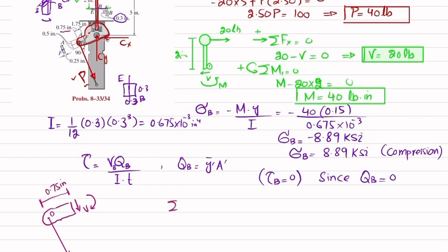So we will find the vertical force, sum of all forces along this direction, which is, this is your Y dash, this is your X dash. So sum of forces along Y dash will be equal to 0, taking the force in this direction as positive. So P is 40 kilonewton, which is downward, so minus 40, and minus V is equal to 0.